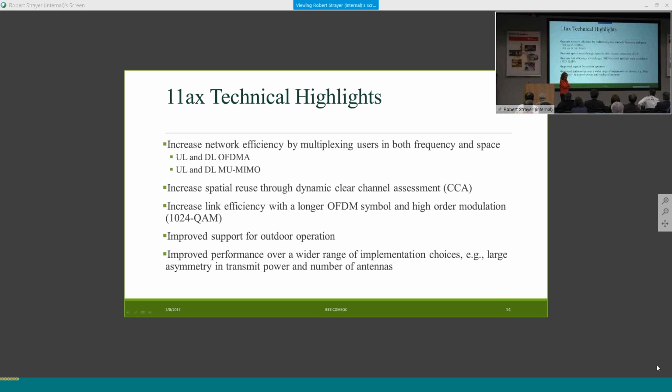So now, MIMO was already there, OFDM was already there. So how did we develop these more efficient techniques? Number one: we had OFDM in Wi-Fi, but not OFDMA, so the whole band was assigned to one user. But now OFDMA is introduced to Wi-Fi. If you have 256 orthogonal subcarriers to create this OFDM, you divide them between users, so each user gets a portion of those 256 points.